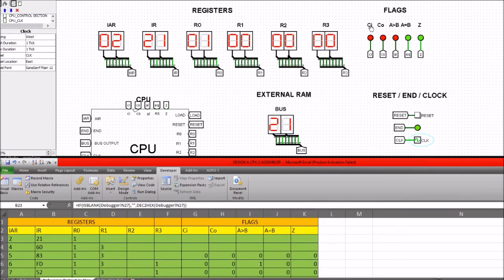Now we don't care what the flags are because it's a data command, and we're not going to run any jump function off of a data command. We're only going to run jump functions off of the ALU instruction, so we don't really care what these say. And again, we can head up along 24 clock pulses, so if you click this 24 times,